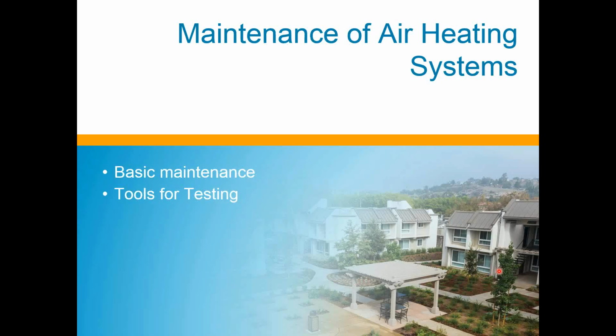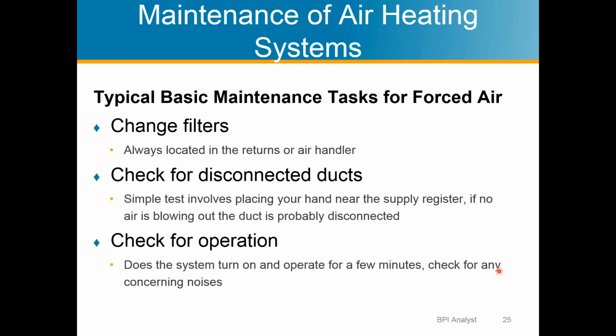So we'll talk about a little basic maintenance. Of course, change your filters. I said last time I would usually leave homeowners many filters with dates on them so they know when to change them. But I try to at least do it at the beginning of the heating season and the beginning of the cooling season. You want to check for disconnected ducts.